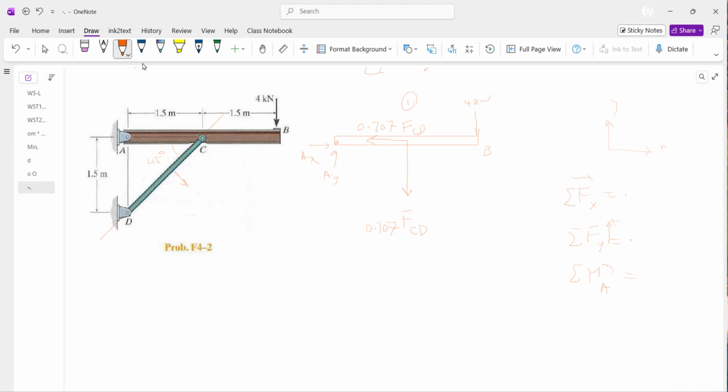Alright, so there is no special order to apply these conditions. I prefer to apply condition 3 first. So what do I mean by net rotation, net forces? Any rotational effects should be written in algebraic positive and negative on the left hand side of the equation, and the 0 on the right hand side indicates that all these net rotation effects can only cancel each other to 0 rotation. That is the condition for stability of the system.